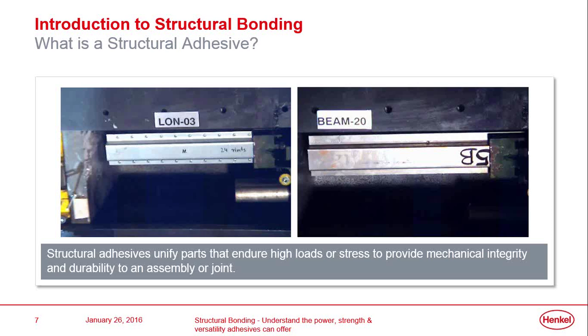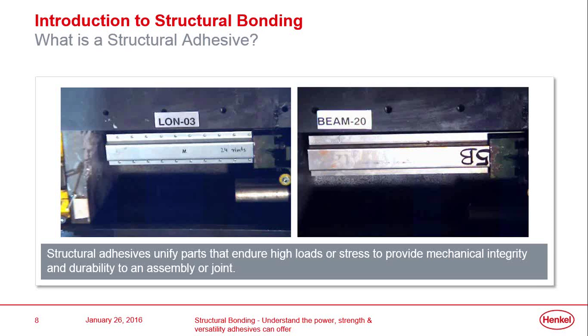There's probably no better example of this improved stress distribution than this one here, which on the left-hand side shows you a riveted box beam, so two top hat stiffeners joined together. And on the right, we have the same geometry, but the flanges are entirely bonded. Now, in the next series of pictures, there is a high-pressure, high-speed ram that will be impacting these as we go through.